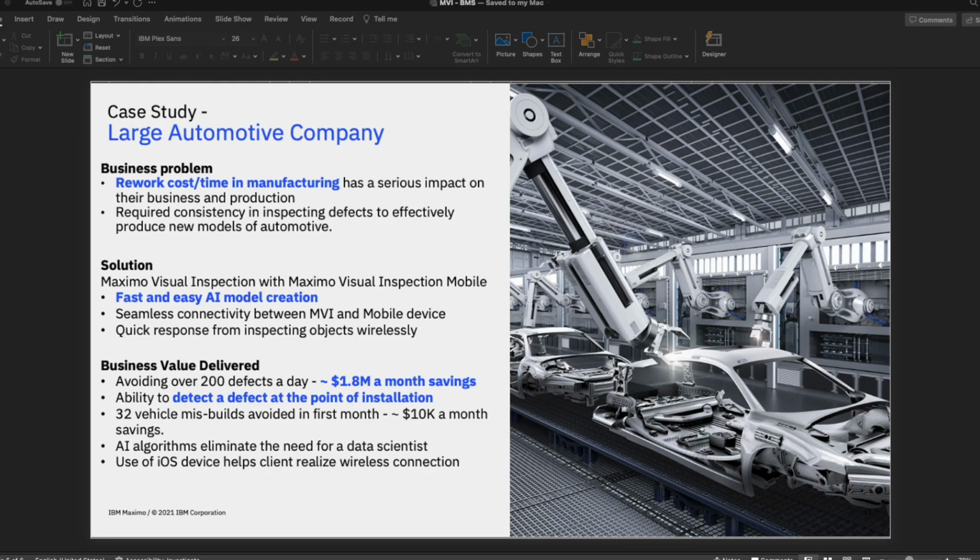And we used that to identify on the bottling line if the bottles were being overfilled or underfilled. Now, each of those bottles, typically you want to have around 12 ounces of beer in each bottle. And so what we did was we took images of each, and if the machine learning model, MBI, showed that the bottle was overfilled or underfilled, it would send a message to the controller to change the pressure of injecting beer into the bottles to fix the issue.